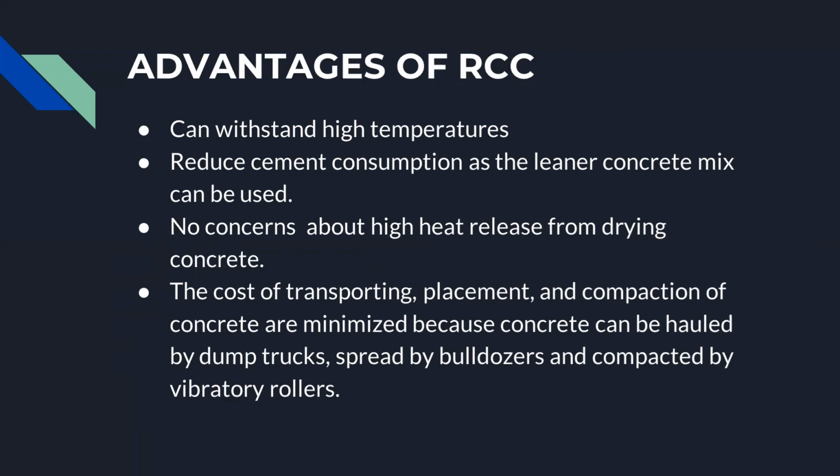The cost of transporting, placement, and compaction of concrete are minimized because concrete can be hauled by dump trucks, spread by bulldozers, and compacted by vibratory rollers.